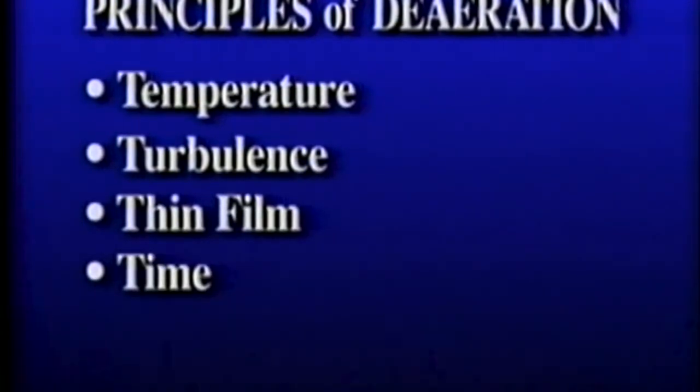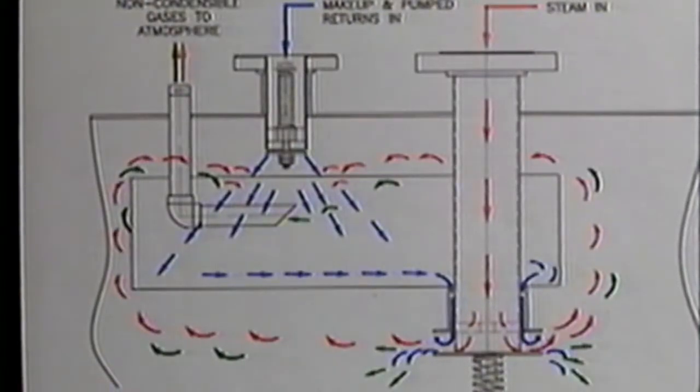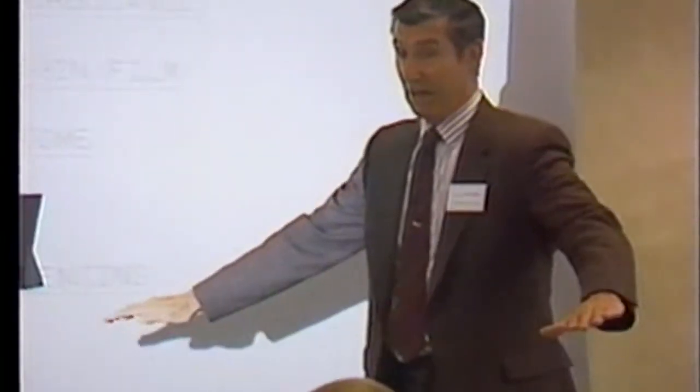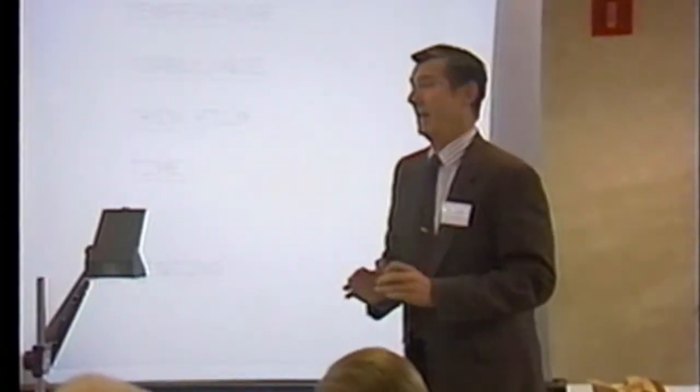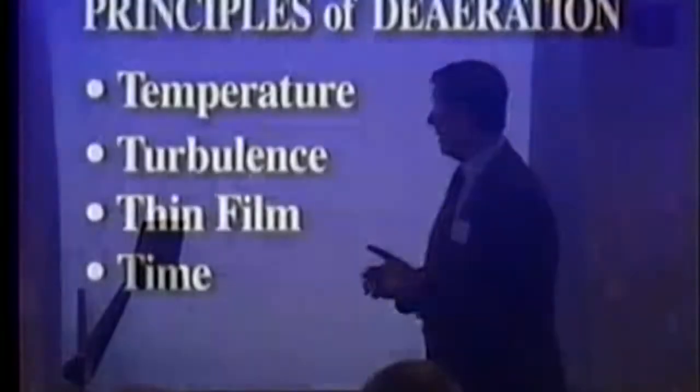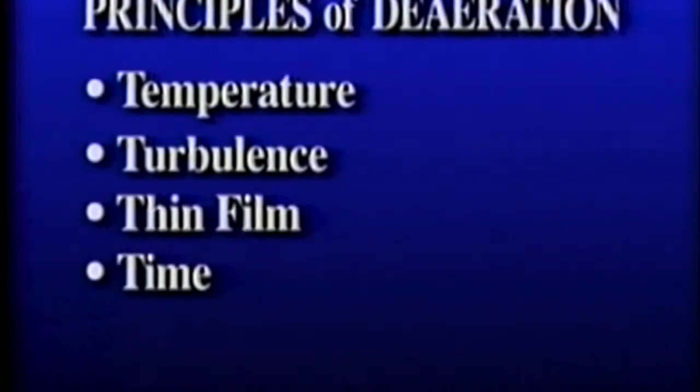And if you have a good imagination, and we'll talk about it in a second because I'm going to show you how our jet spray works. The jet spray sprays water in, hits a pan, goes through a thing, hits another nozzle, exploded out, and hits the water level. Now, once it's done that, it's through. You can't get any more oxygen out of it with a jet spray. It's all done. That's why they're kind of critical. There are several applications they shouldn't be used for, and we'll talk about that too. But the point I'm trying to make is, how much time are you talking about? Second and a half, 2 seconds?